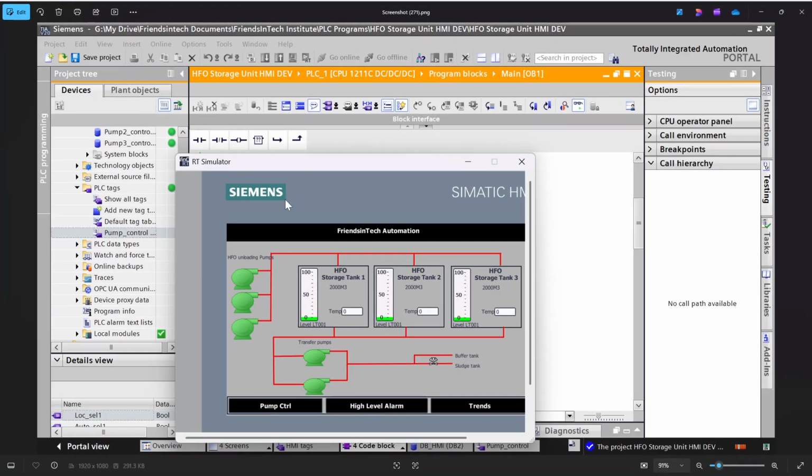So we had this process overview window where we had 3 tanks and I don't know how many of these, 5 pumps. So I want to create a UDT for this tank, storage tank 1, storage tank 2, storage tank 3. So I have 3 of them, but I want to create one template, just one template for this tank, then reuse it over and over.